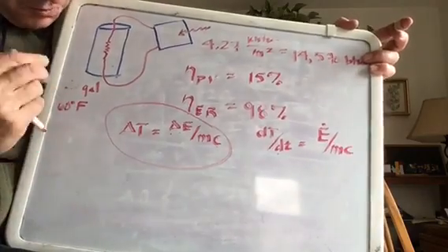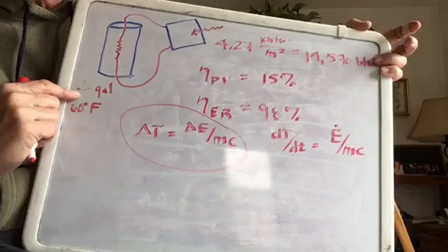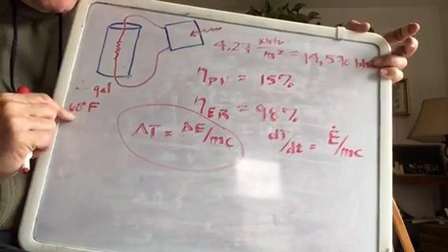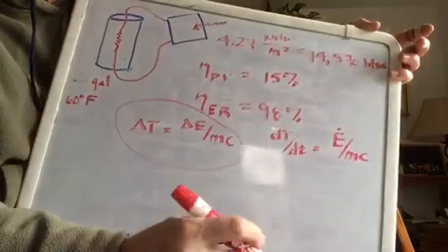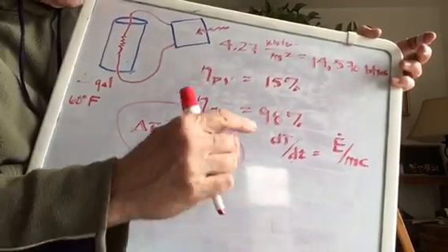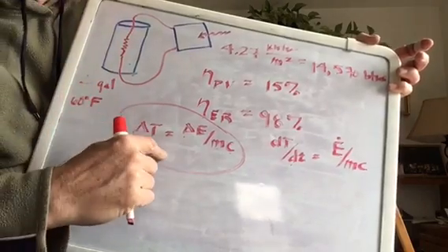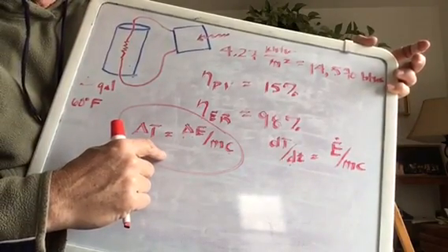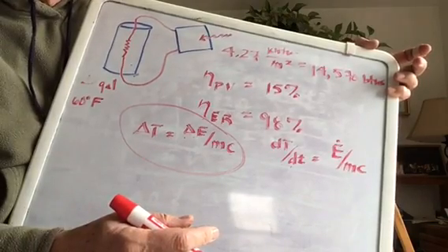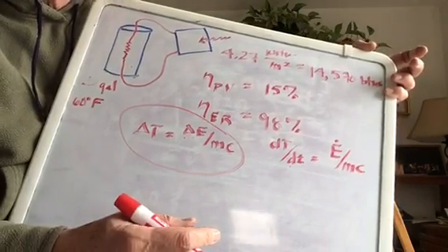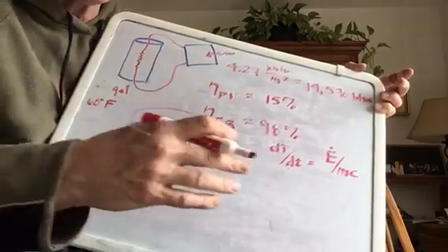So what we're going to do, again, I'm sorry you lost it here. We got 20 gallons of water. A gallon of water is about 8.33 pounds. It starts at 60 degrees Fahrenheit. Okay. What if we have this much solar available, 14,570 BTUs? How much of that solar ends up in the water? Okay. And then what is the consequence? What is the resulting delta T of the water? So I'd encourage you to go ahead and pause the video and start getting to work. I'm going to work this out in little bits, and so you can go back to the video and see if your work is correct.